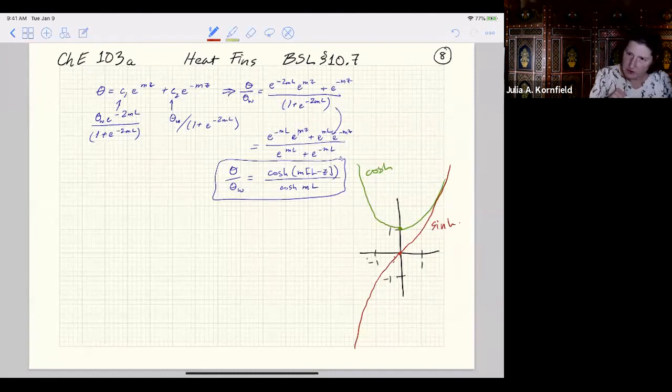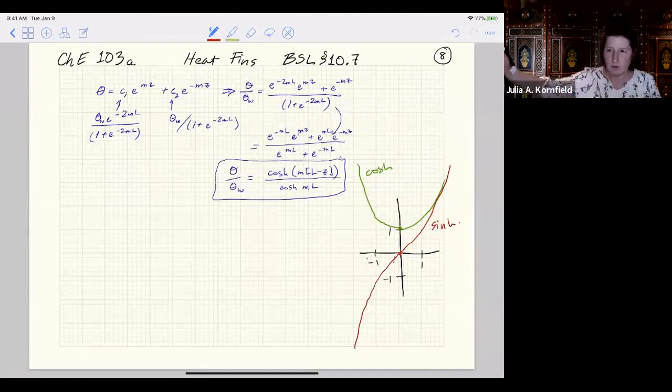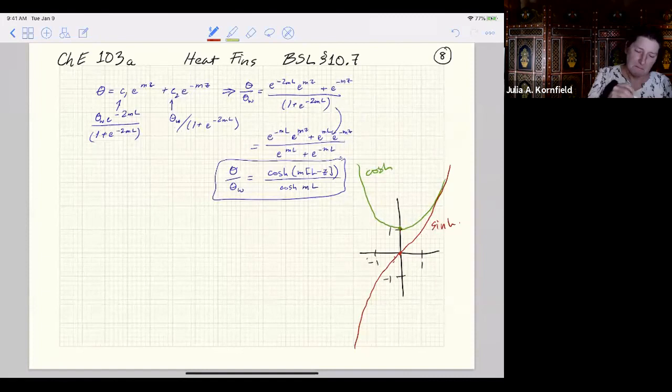And one of our boundary conditions is 0 slope. And as we've formulated the coordinates here, that boundary condition is imposed at a non-zero argument at z equals L. But we say, hey, sinh never has a slope of 0. Cosh has a slope of 0, and it's at the origin, at the argument equals 0. Can we move our boundary conditions around, flip them, so that we have cosh at 0, satisfying us that 0 slope boundary condition? Okay, let's try it.